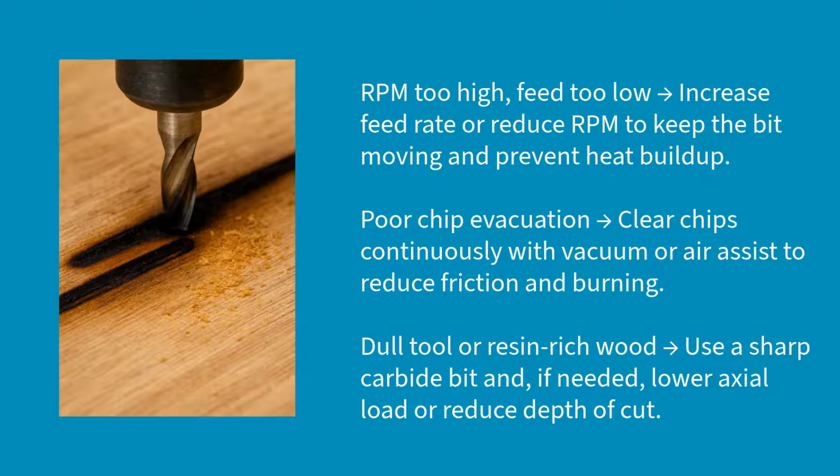Also, poor chip evacuation, so you want to make sure that you're clearing chips as they're being created to reduce friction. And then dull tool or resin-rich wood, use a sharp carbide bit, and if needed, a low axial load to reduce depth of cut, or reduce the depth of cut. Essentially, if your tool is dull or you're doing a resin-rich wood, you want to use a very sharp bit and reduce your depth of cut.